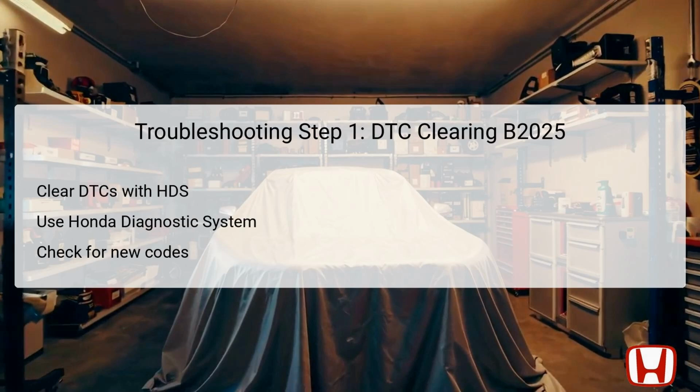The first step in troubleshooting DTC B2025 involves clearing the diagnostic trouble codes using the HDS, or Honda Diagnostic System. This system is essential for reading and diagnosing vehicle faults. After clearing the codes, it's imperative to turn the ignition switch to the lock position and then back to the on position.